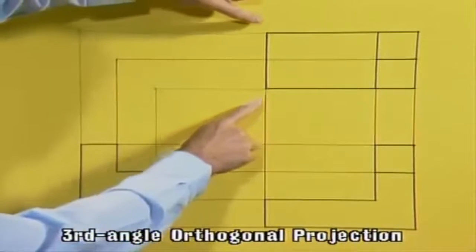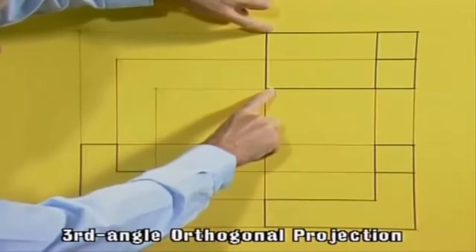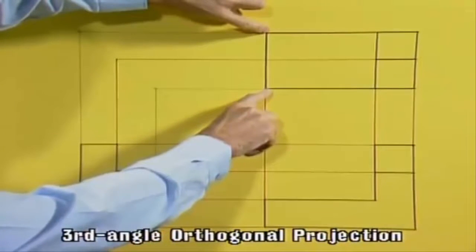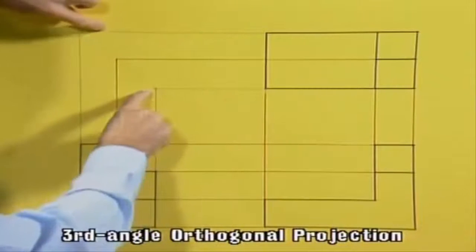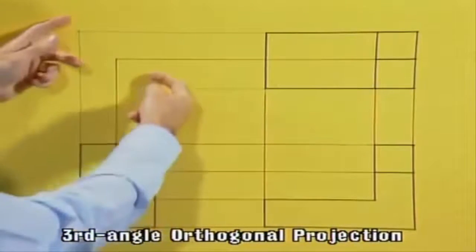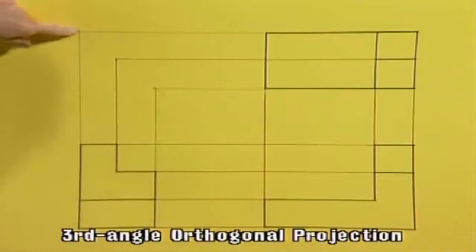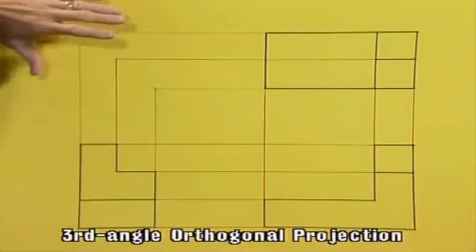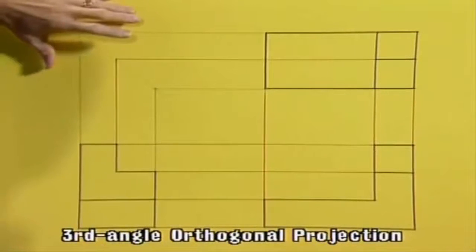To set the projection system up, we project across from the 2 outside dimensions of the top view horizontally, and the 2 outside dimensions of the side view vertically. Where they intersect, we draw a 45-degree line through. That's the setup for the projection system.